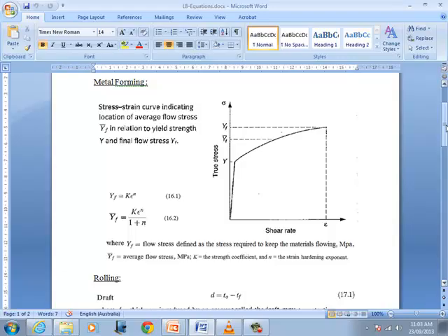As we pass this point, which is the yield strength, if the magnitude of the stress is beyond this point, then there is a permanent change of shape, right? Meaning that if the material is stretched beyond that point, it returns slightly toward the original length, but not exactly to the original shape. There is some permanent change of length which stays in place. The same applies for any other type of change of shape.